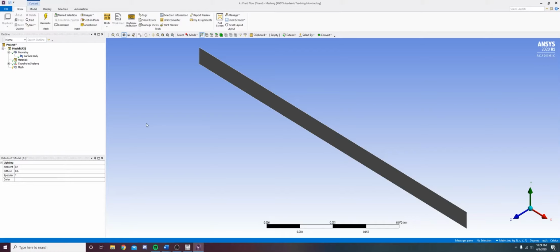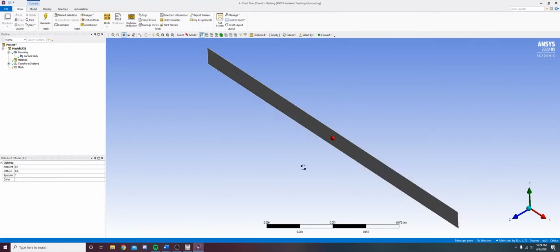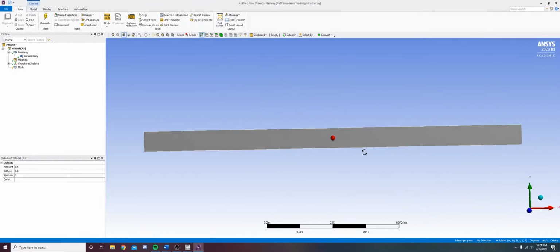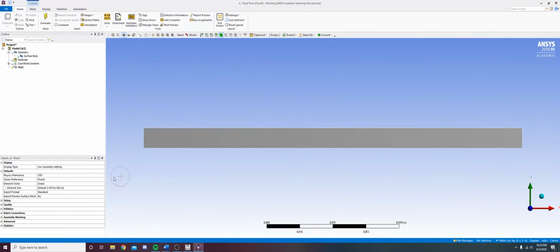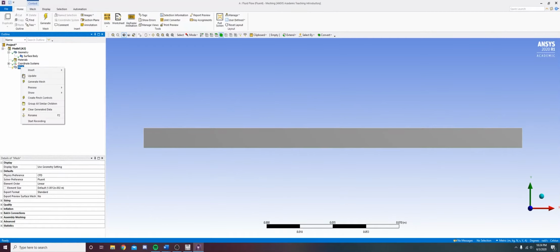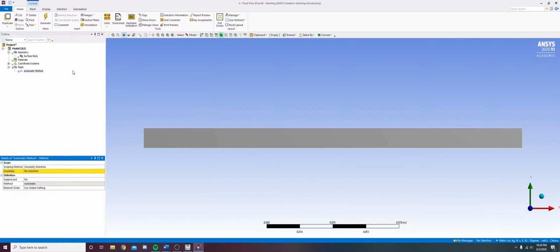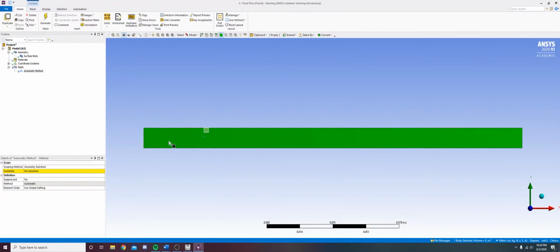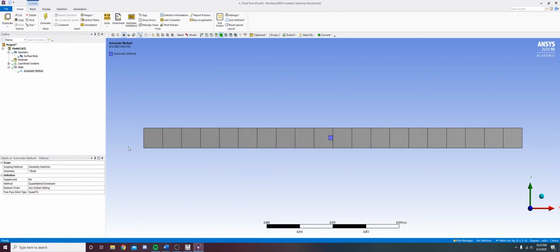So here's the basic meshing console. You can see it automatically loads in my geometry. So what we're going to do first is we're going to just let the computer do whatever it wants to do, and we're going to see how bad this mesh is. So mesh, insert, method, and we're going to click this piece of geometry, and you're going to see the apply button. So apply that selection to it, and go. Generate me a mesh. Terrible.